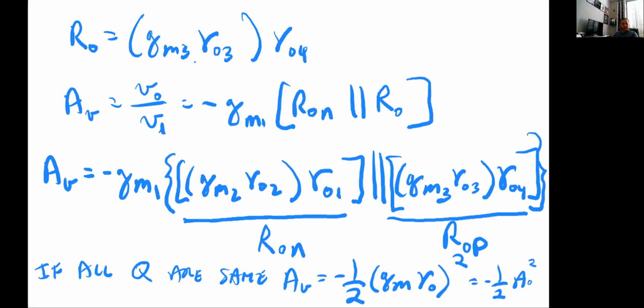Now let's pivot and look at another circuit that is very important that we have talked about, which is the source follower, because at some point we need this current amplification to drive load and isolate that voltage amplifier whose gain relies on the load, isolate it and drive whatever load is there. We don't want the gain tied to the load. So the source follower allows us to do that.